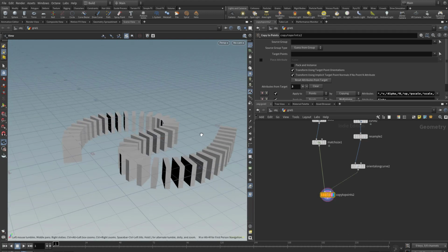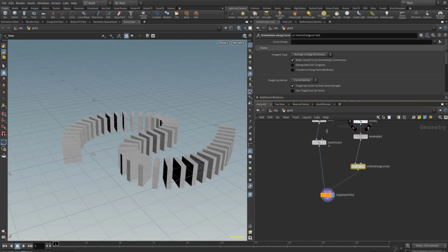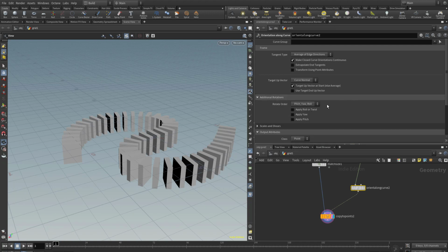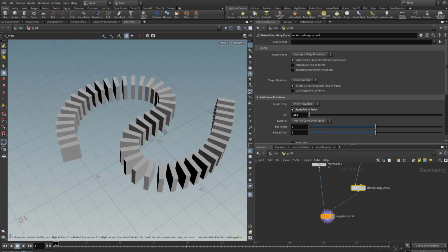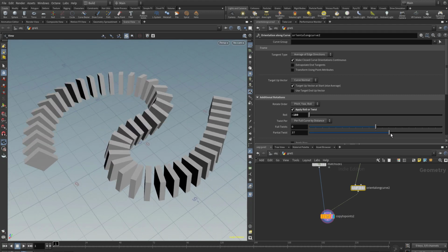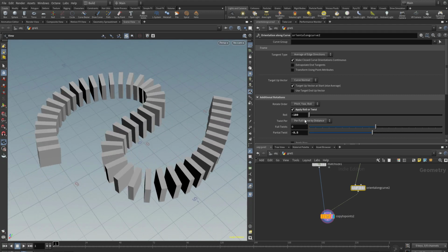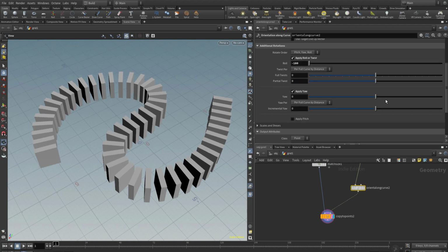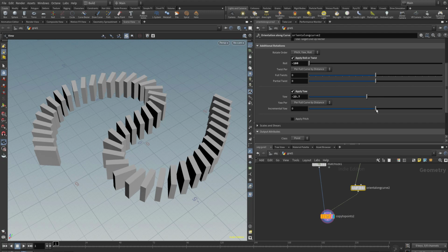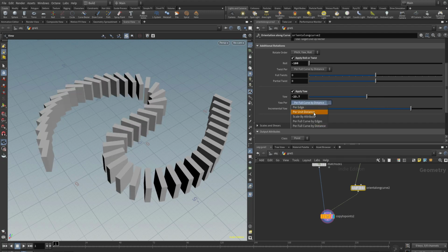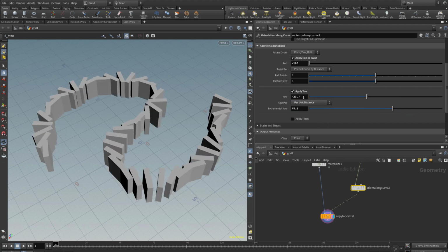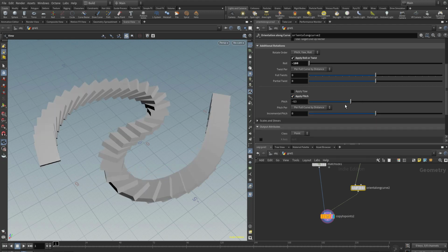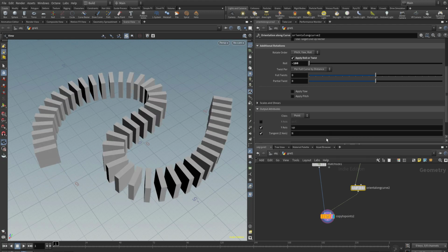Now it's upside down. So what you can do is you come into orientation and take the roll value, and we'll make it 180. Okay, so you can do this. Then you have other options, like you can twist it, and you can twist it in different axes. So I can just take this and spin it around. I can give it additional values. Okay, so this is fine.